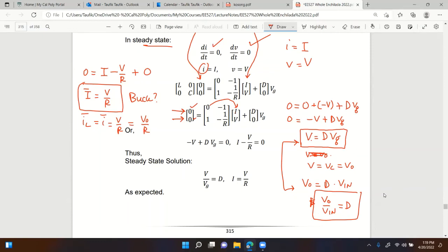Yes, right. Remember, especially if you've taken 410, you should know this. A buck converter has, on the output side, this. That's our output voltage. That's our R. That's our C. That's our L. This is our current IL. The average value of IL in steady state is equal to V out over R, isn't it? As you learned from E410. What happens with IC? Am I ignoring IC?